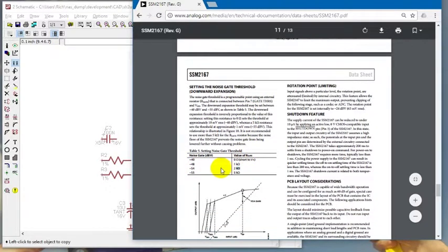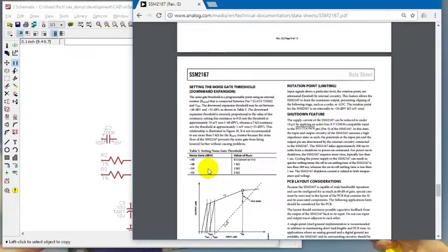So here's my threshold at minus 54 dBV, right? So remember, in volt mode, a factor of 10 is 20 dB. So 40 is 10 times 10, so 1/100th of a volt, right? So 10 millivolts. And then 55, as you're getting down to 60 at about 10K or so, would be 1 millivolt. So anything below an average value of 1 millivolt would get muted automatically, right? So I'll start with 2K for the gate threshold, right?